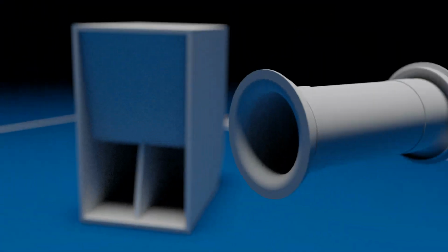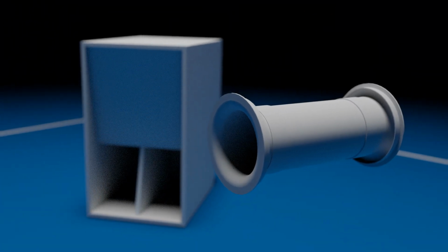So the reason I'm grouping flares and tapers together is that they're both used to manipulate velocity and acoustic impedance. In certain applications they're referred to as horns, and the main difference between the large ones like you see in pro audio and the small ones like you see at the ends of port tubes is their relationship to the lengths of waves passing through them.